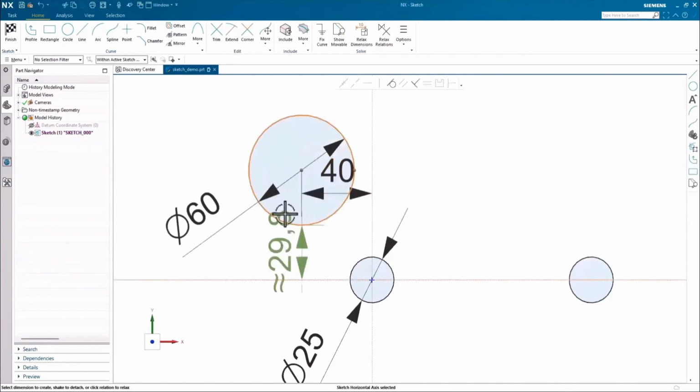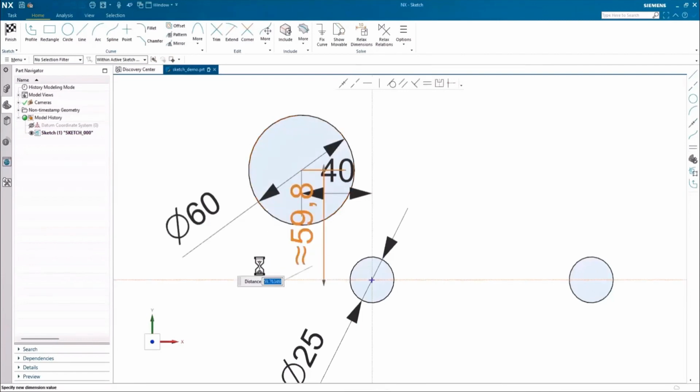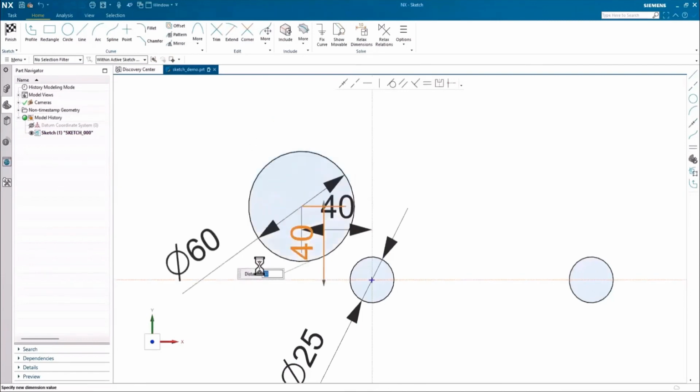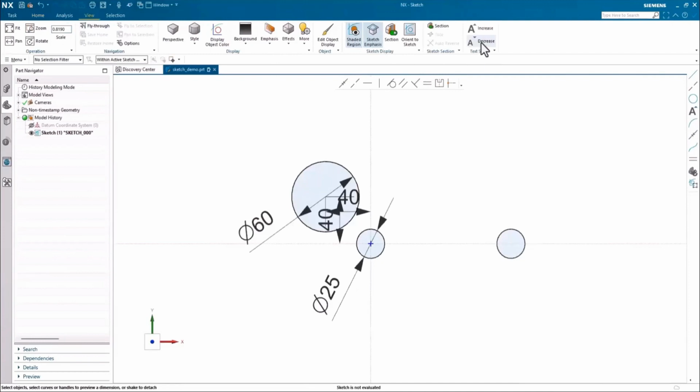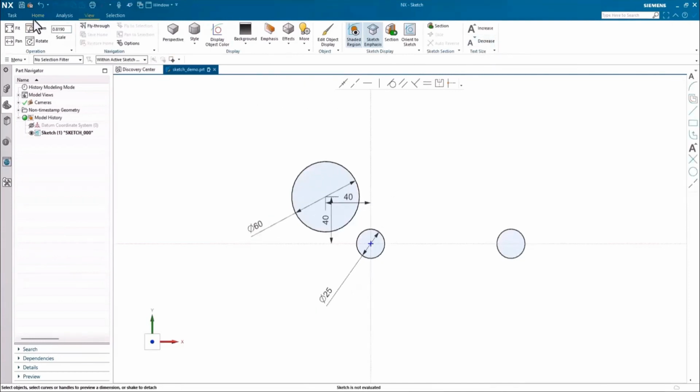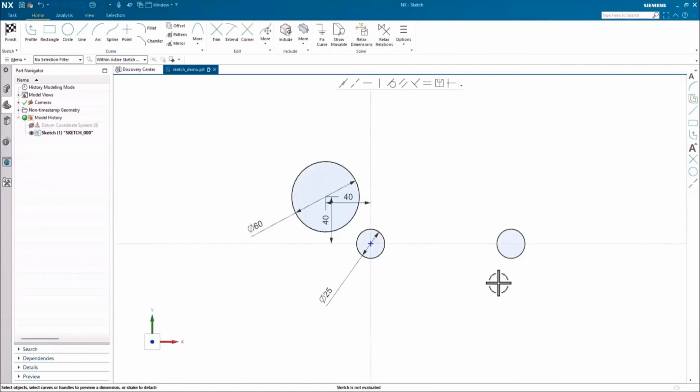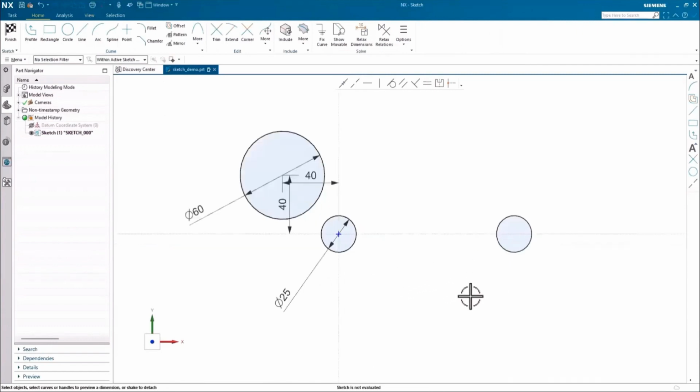As you go in, where maybe we want the center point of the circle, you can touch on the circle. It will highlight those control points, and then you can pick the control point. One thing also is you see the dashed lines as the center, thinking of that as location 0, right? In the past, you could just sketch into space and put them on there.